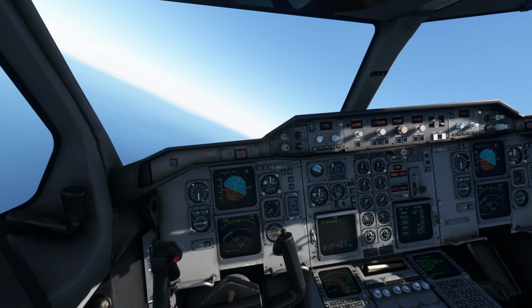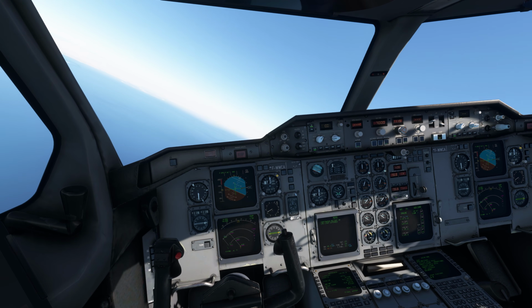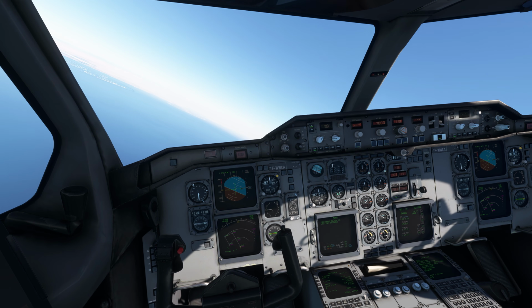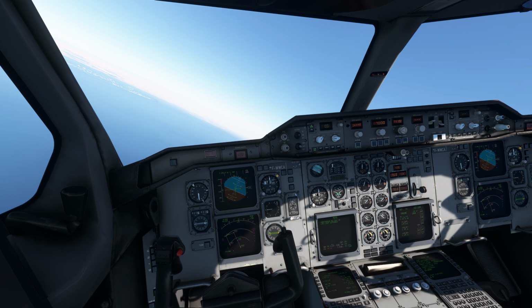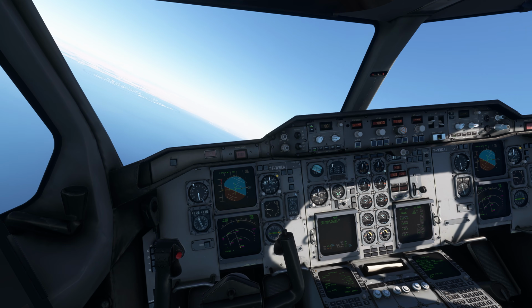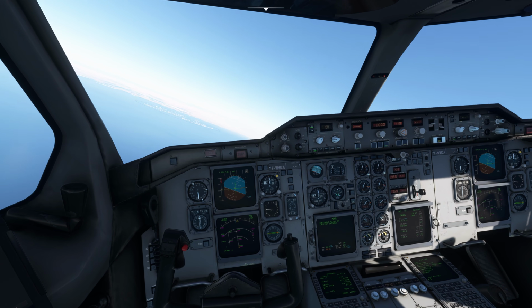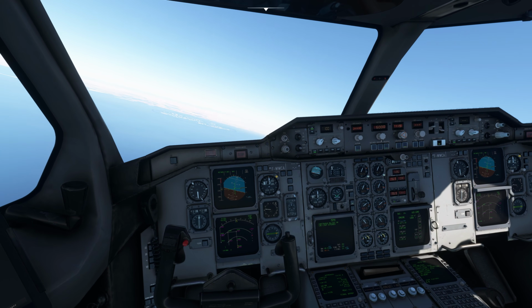If you align and you're going to touch the runway at the right point, there are 2 white and 2 red PAPI lights, which I will show you in this video. If it's like this, then you can proceed with the landing. Otherwise, you have to call it a missed approach, or go around and come back. I will also try to do a video in which I will tell you how to perform a go around.